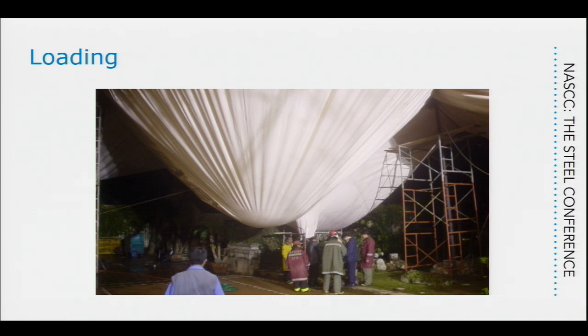Now, for some projects, one of our partners is doing one of the Qatar stadiums, and they had a lot of fabric for one of those stadiums. So what they requested is that the manufacturer do a 2 meter run, so a 2 meter width, because they didn't want the amount of welding that they were having to do, the number of strips was a lot more than if they just said do a larger run with less seams on it. Generally, I say it's 3 feet. It's a 1 meter width usually.